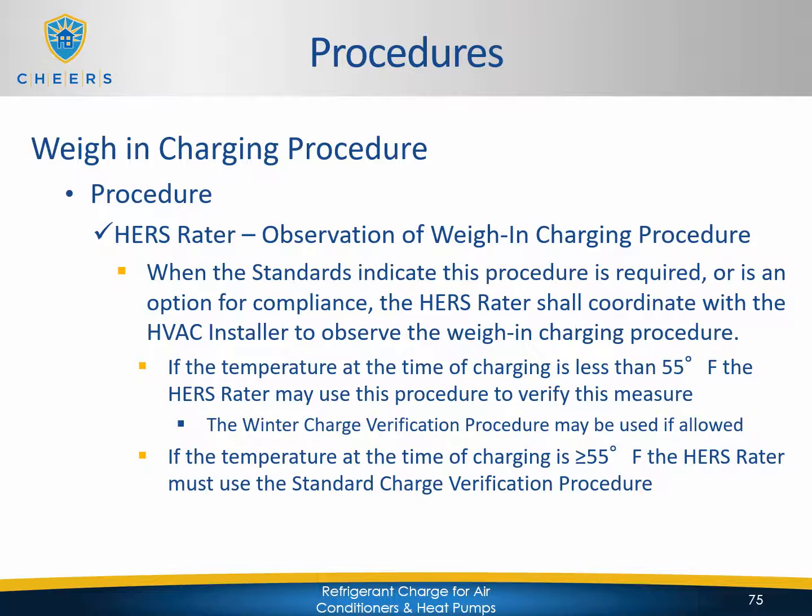So there's a couple of options, but the main thing to know is that if it's less than 55 at the time of charging, you'll likely want to be on site and observe that weigh-in charge procedure. If not, you'll have to come back later when it is within the range for the standard and then perform that standard charge verification procedure.